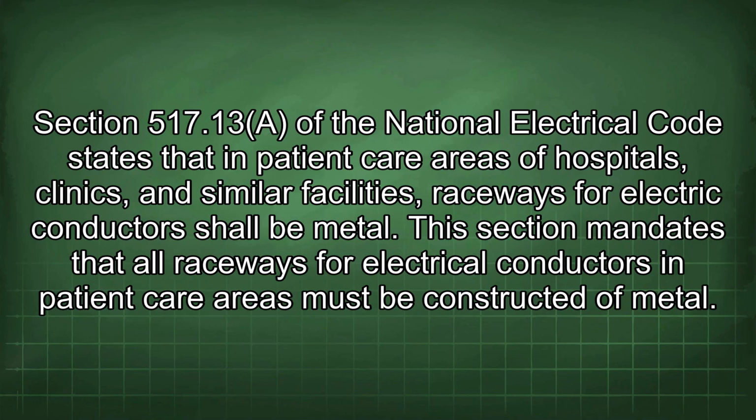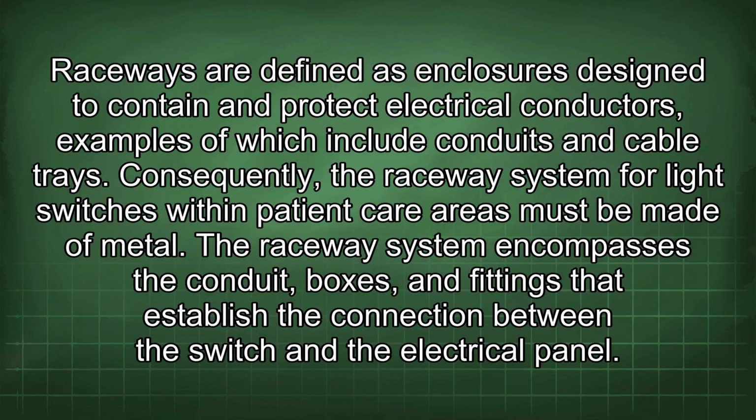Section 517.13 of the National Electrical Code states that in patient care areas of hospitals, clinics, and similar facilities, raceways for electric conductors shall be metal. This section mandates that all raceways for electrical conductors in patient care areas must be constructed of metal. Raceways are defined as enclosures designed to contain and protect electrical conductors, examples of which include conduits and cable trays.